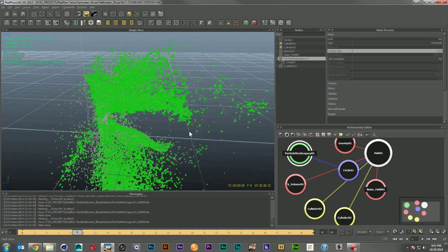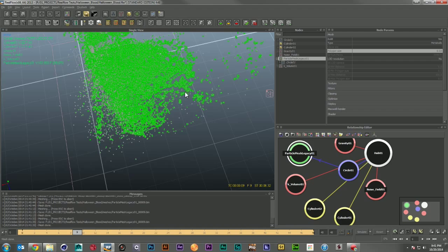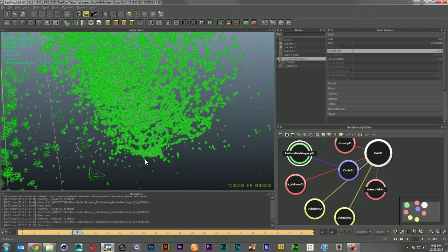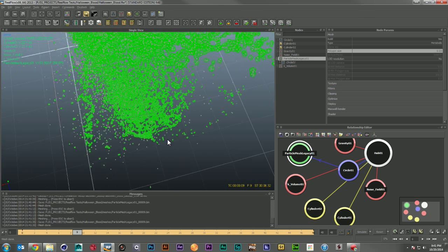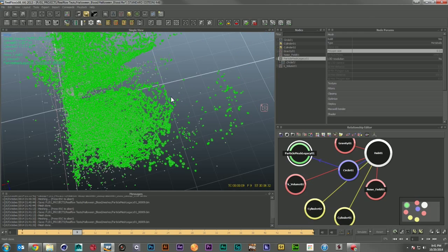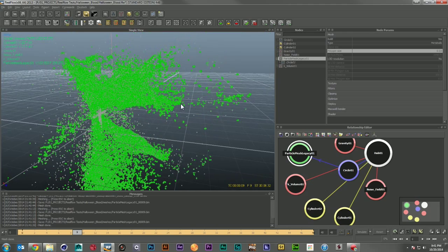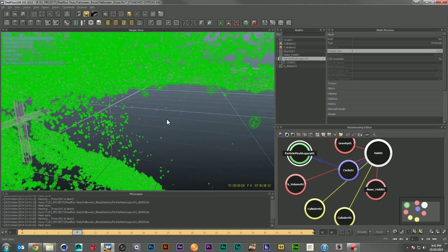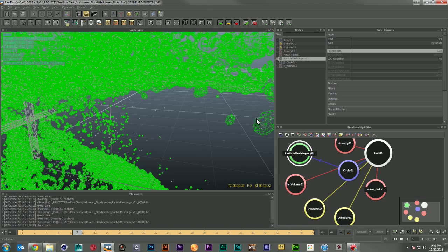Now we're starting to get ballpark of where we want to get to, because we're starting to see that the mesh is much, much closer to our particles, and it's not making one ginormous shape anymore. So let's go ahead and maybe drop our polygon size down to 0.02, build it again. There we go. We're getting nicer, smoother geometry.